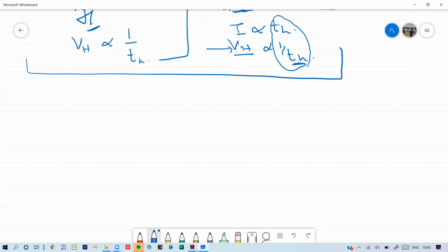The shape should not theoretically have an effect on the Hall voltage, but it has been seen that in reality, the geometry of a Hall sensor does affect the VH output. That means Hall voltage is what you measure in the output. Then you can convert the voltage into current, or convert that voltage into another signal, in a frequency, using different circuits. So VH also depends upon the different geometries of the Hall measurements.